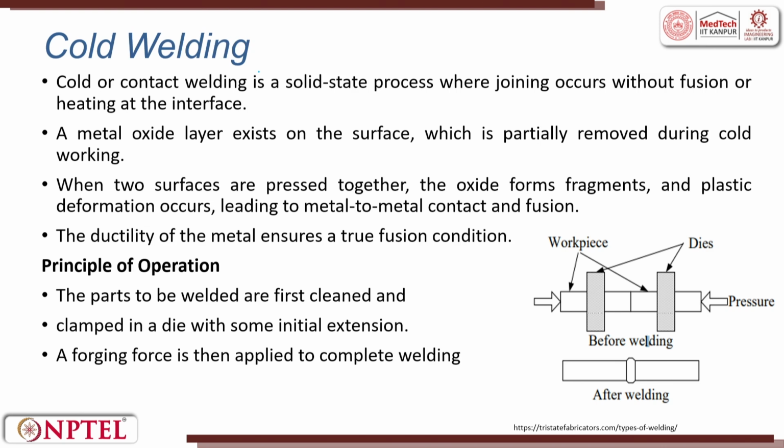Cold welding process. Cold or contact welding is a solid state process where joining occurs without fusion or heating of the substrate. So, here what happens? You have a die or a moving plate, it can be a fixed plate, it can be a moving platen. And then what happens here? We try to take these two close to each other and apply a huge pressure. This huge pressure leads to joining.